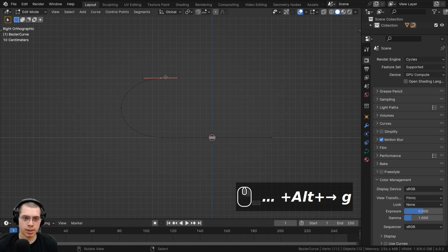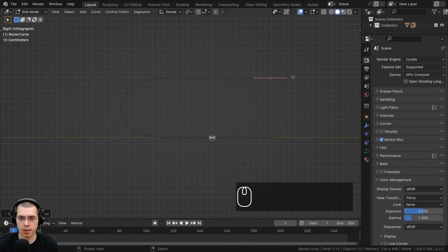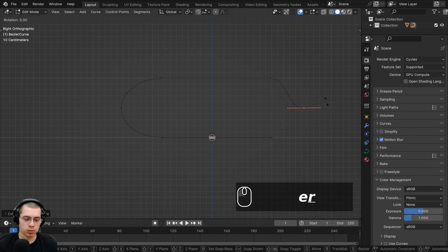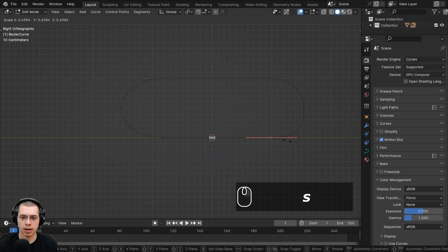And then I will select this handle here and extrude it again. We can click with our middle mouse wheel and bring that over there. So you can see there is 1 grid, then here's the other grid, and then we're just going to have it be half of this grid. So I'll extrude it to about there, rotate that over by 90 degrees, and then if I select both of these handles, I can press the F key to fill that, and I can also scale these handles down because they're a bit too big.